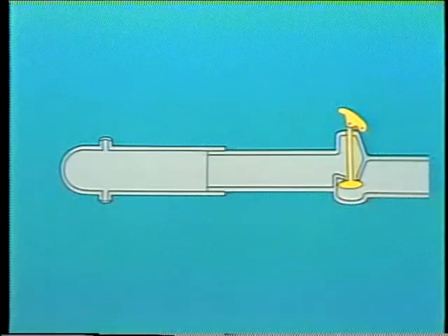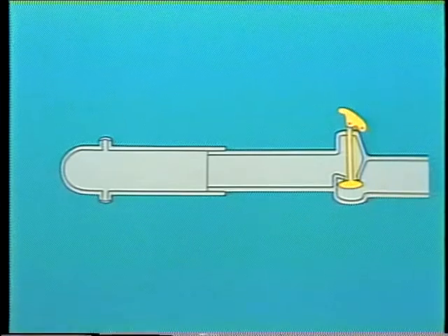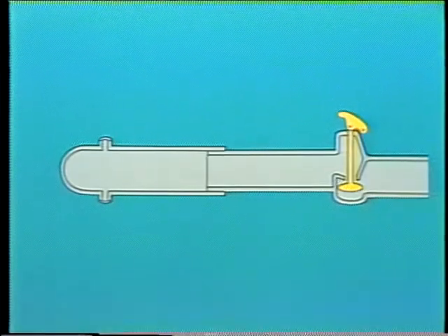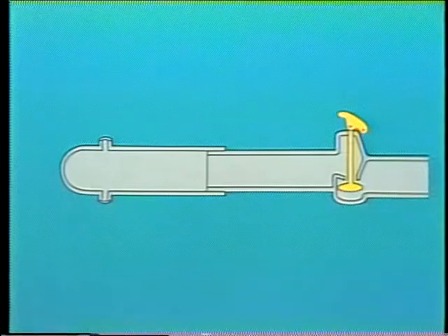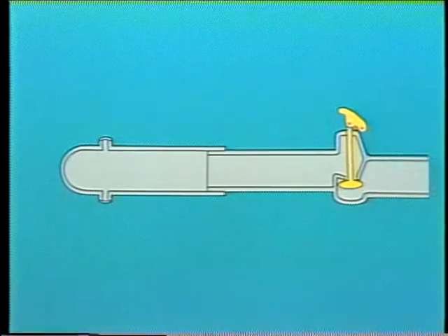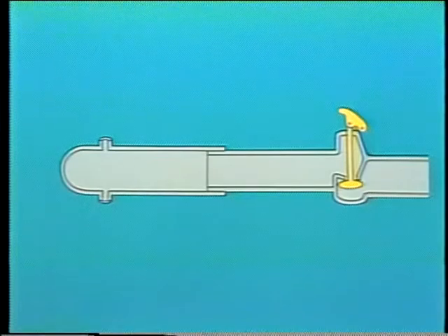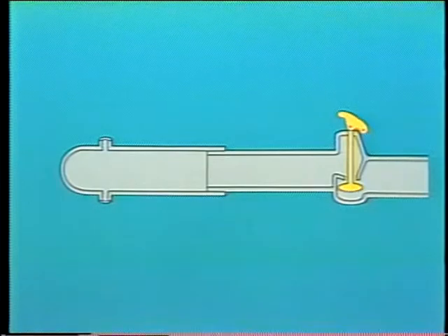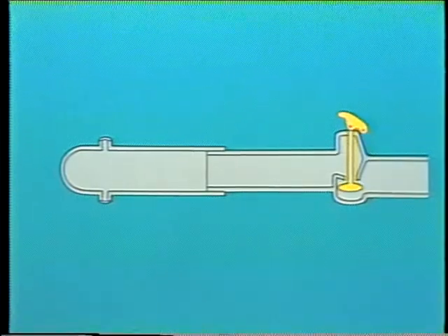In the last section, we identified the 3 basic types of soot blowers, and we looked at the differences in how and where each type is used. In this part of the unit, we'll examine more closely how each type operates and the differences and similarities between them. The most basic soot blower is the fixed soot blower. It is operated simply by opening the valve for a predetermined period. This amount of time is chosen according to certain factors such as the soot blower's location and the area it's supposed to clean. The valve may be operated electrically, by compressed air, or it may be manually controlled.